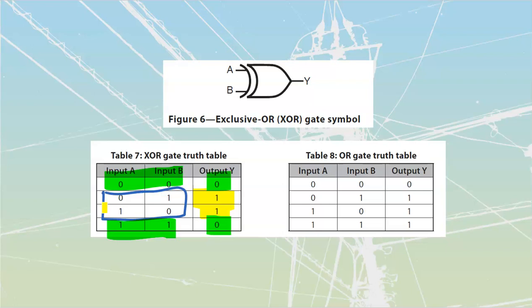Where do we utilize these? These are used for interlocks on a lot of systems. We've got a bunch of systems you would have covered back in level 2 under motor control. Yes, that's where we're going with this. You would have covered reversing motor contactors. Should we ever operate a forward contactor at the same time as a reverse contactor? Absolutely not. It should only ever be operational in forward or in reverse.